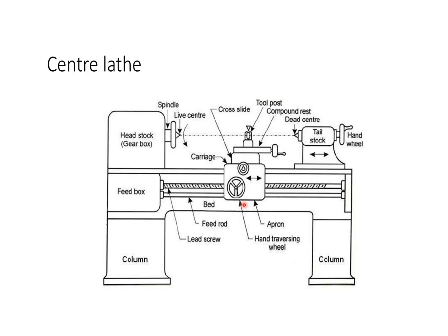Next, the compound rest. For compound rest, it is mounted on cross slide, carries a circular base called swivel plate, which is used during taper turning to set the tool for angular cuts. The upper part known as compound slide can be moved by means of hand wheel. Then the tool post. So it is fitted over the compound rest. The tool is clamped in it.